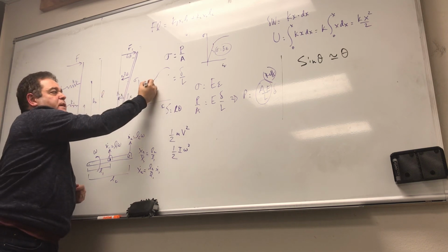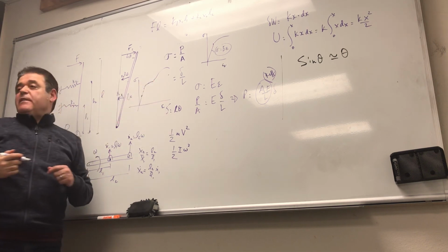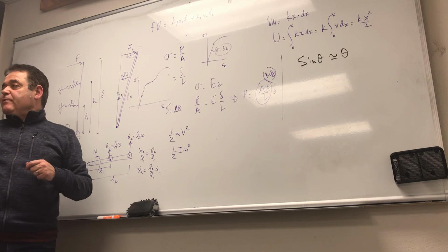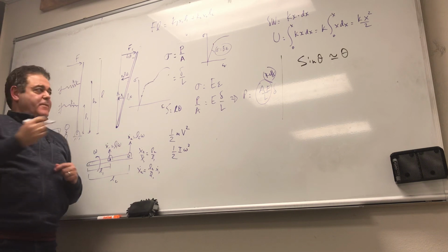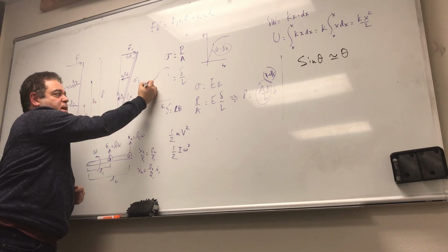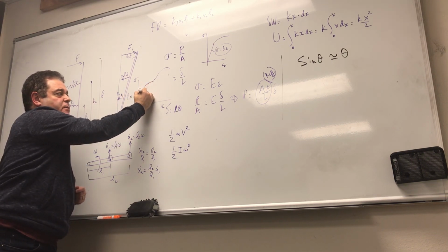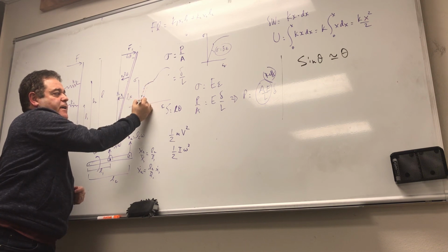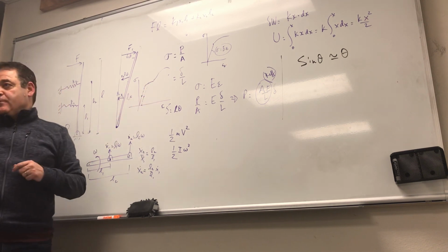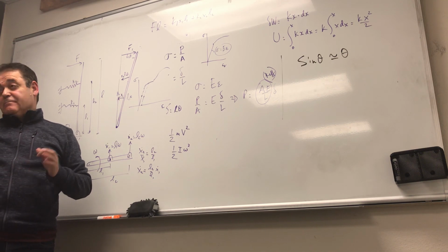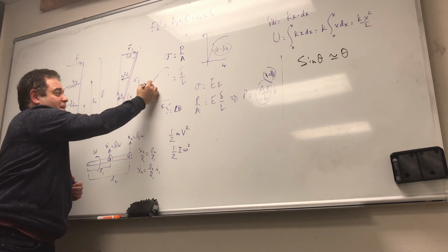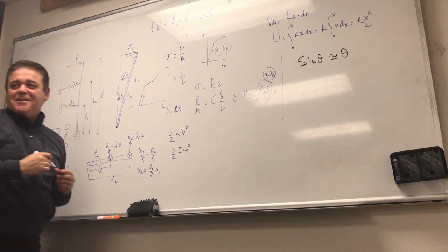But if you load it such that you get a little bit of deformation, and you try to remove the load, in which direction do you unload? Remember, from strength of material, you always unload in a line that is parallel to the loading one, right? And then here you cross a point where you have what we call a residual strain, right? I know that's probably a lot. Going back a few years.